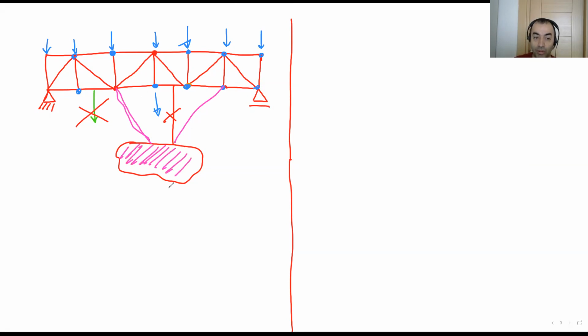This is important. If you did this, for example, you can say, oh, I don't care about the rules, I can connect my member to the middle of this member. If you do this, you can break this member down. So it depends on the weight. That's okay, but you apply a load which is not considered in design. As an engineer, we only transfer the loads from the joints. So our structural members, these straight members, carry only axial force.